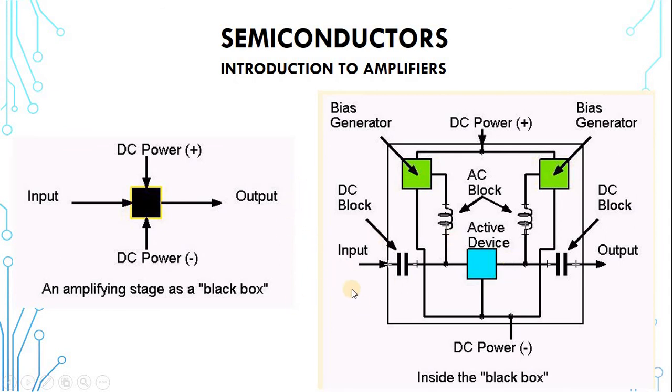And what you want to amplify is your audio, which is AC. It is alternating in nature. You want to amplify it. So there's a tendency that because the circuit producing the audio has a DC supply to it, there may be some DC components in your audio which you don't want to be amplified. As for the amplifier, whatever you feed in, it will amplify it. So when the DC which is polluting your audio signal gets to the amplifier without being blocked or filtered out, the amplifier will amplify everything. You hear the sound, but there's going to be some noise inside.